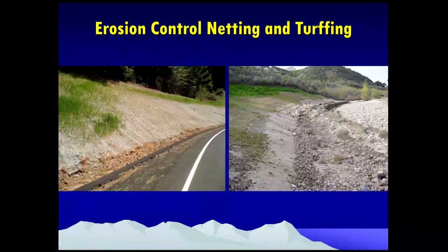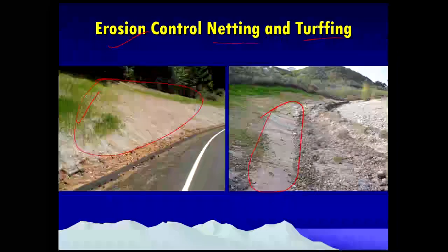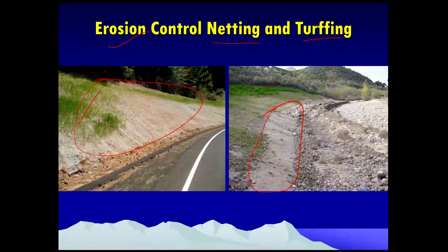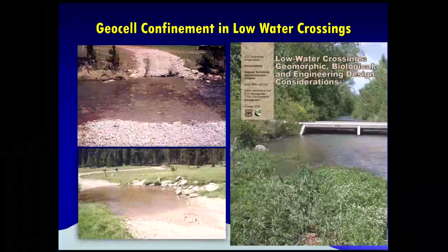So this is the sequence, the subgrade separation and reinforcement functions, you can see. Not only that, this material can also be used in erosion control as well as in netting and turfing. You can see erosion on the banks of a natural water stream. Here you can also see very nice vegetation, and netting and turfing can also be given. It is used in slope stabilization, especially embankments, mostly in coal mining areas where they dump the excavated material in heaps and make the plantations. This material can be used there too.